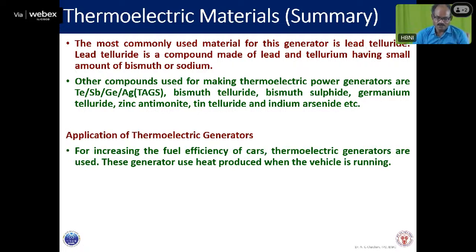The applications of thermoelectric generators are for increasing the fuel efficiency of cars. A car has an engine which is very hot, so you can put a thermoelectric generator there, so that heat which otherwise goes to waste can be utilized in power generation.